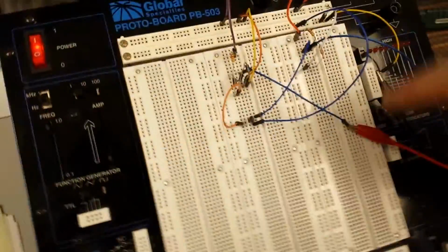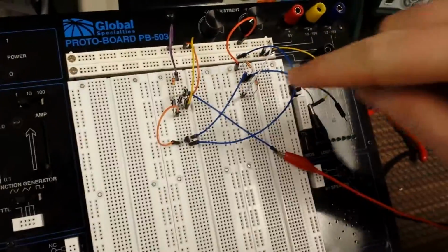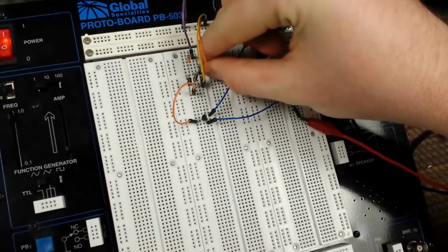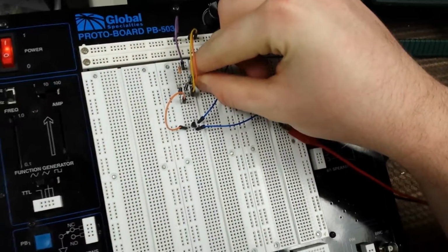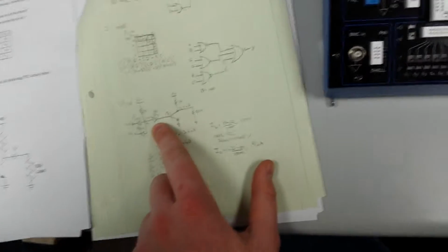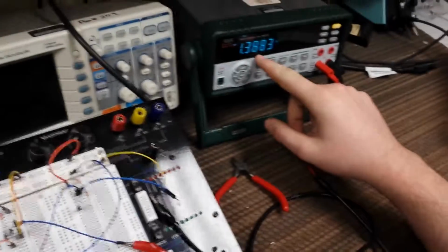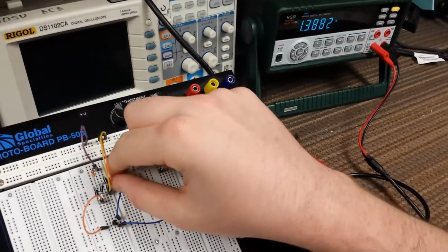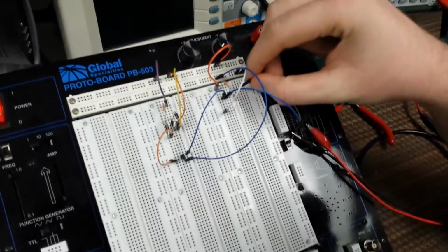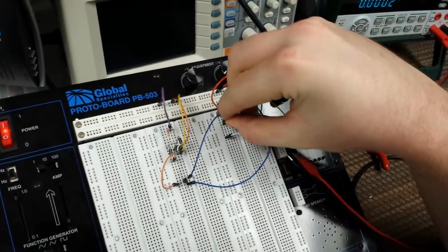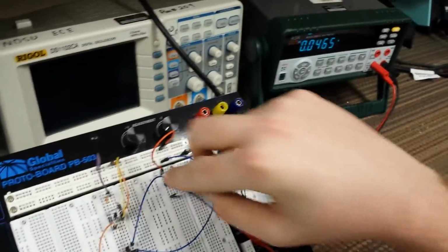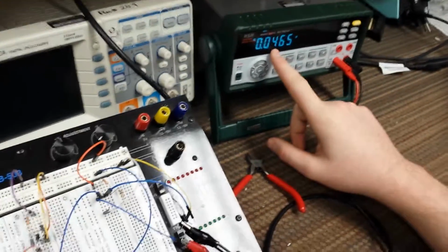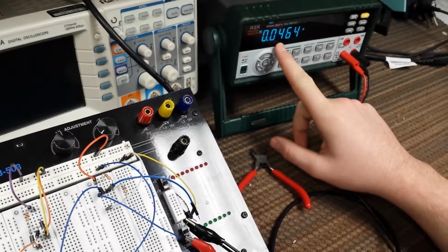Then going over to our experiment. So this is our circuit we built, and right now I'm looking at the junction of the node between the 3 diodes, and it shows that we are at about 1.4 volts, which is good. That means that our diode and our transistor are on. Now if we go over to our collector of our transistor, we can see that it's less than 0.2 volts, meaning that the transistor is saturated.